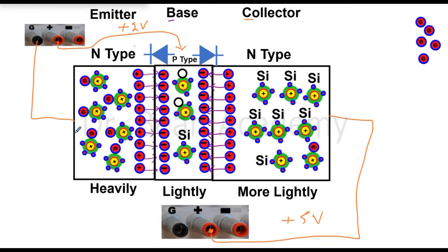And then I will connect the emitter with the ground of this power supply, so that the emitter is common to the base and collector. Now let's see what will happen. First we can check the emitter base junction here, and let's see what is the mode of operation.